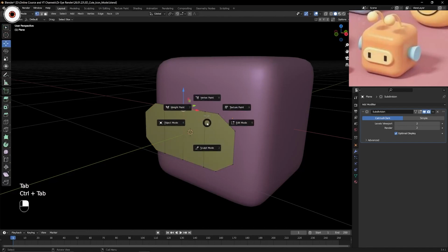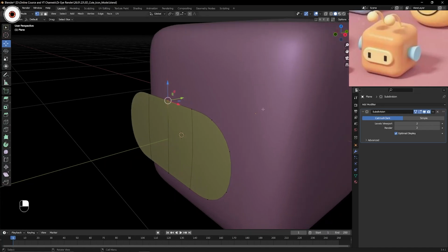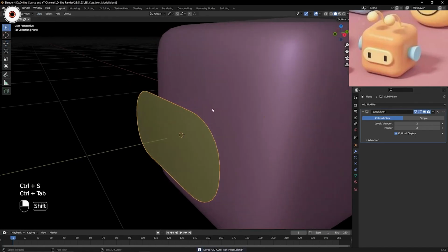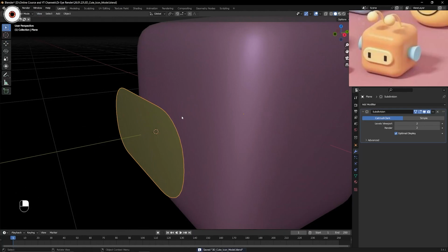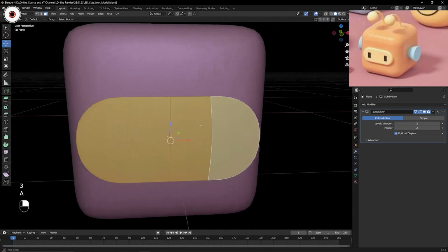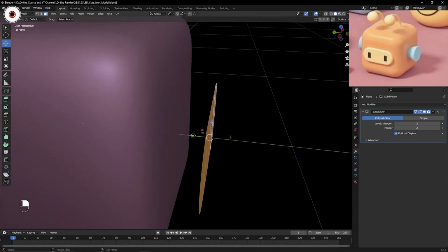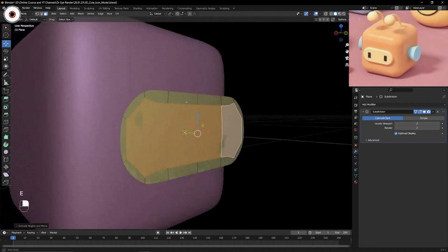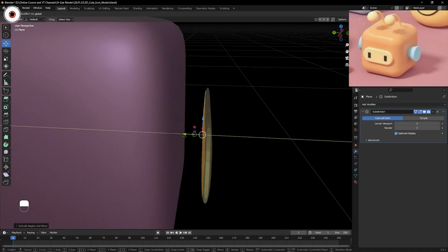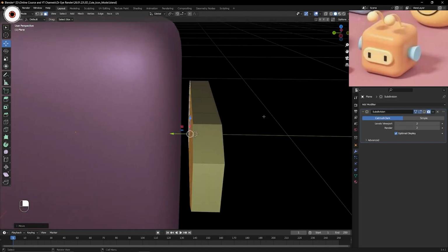and we are going to go in the edit mode. Okay, so the next thing which we are going to do is to extrude the mesh. Okay, so we are going to select the whole thing by pressing A, then we are going to extrude in the Y direction. Okay, so we are going to press E on our keyboard. Okay, and like this. So for now, try to disable this one.